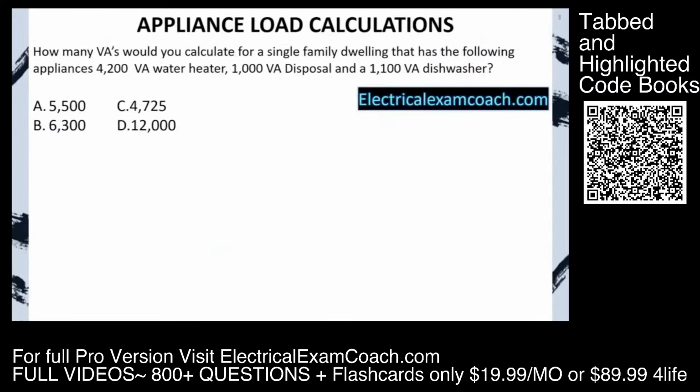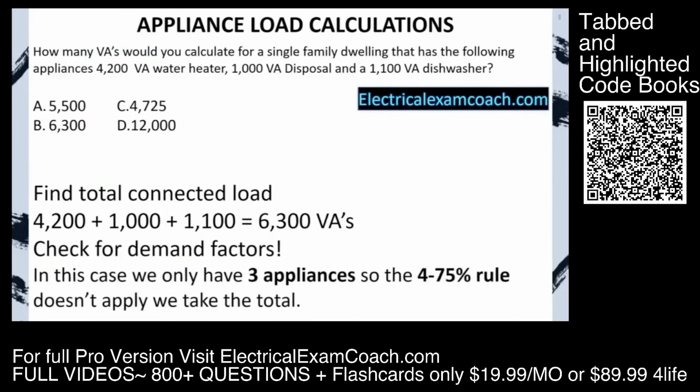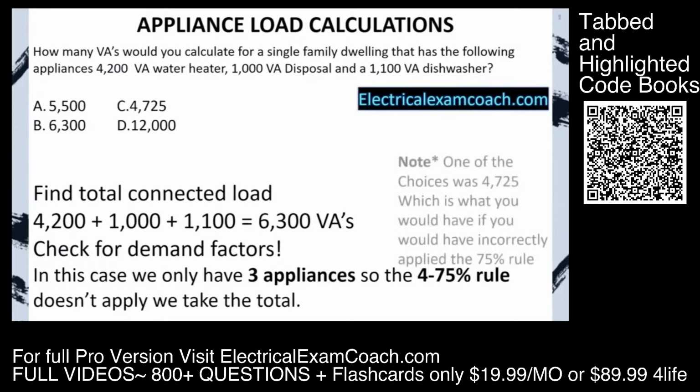How many VAs would you calculate for a single family dwelling that has the following appliances: a 4200 VA water heater, a 1000 VA disposal, and an 1100 VA dishwasher? First, we're going to find the total connected load. We total all that up, it equals 6300 VAs. Now, we check for demand factors. In this case, we only have 3 appliances, so the 75% rule does not apply, and all we have to do is take our total.